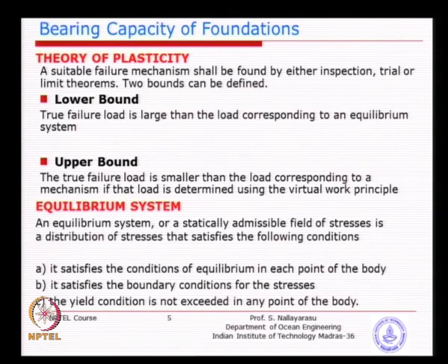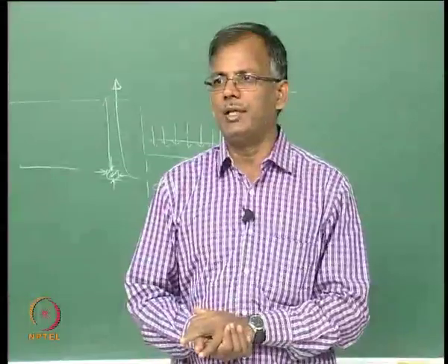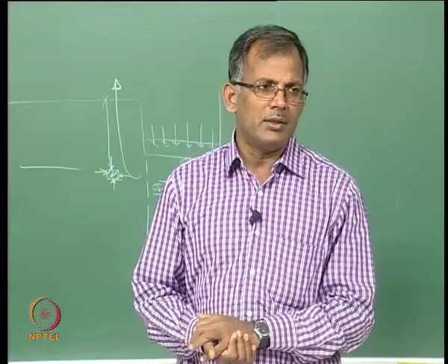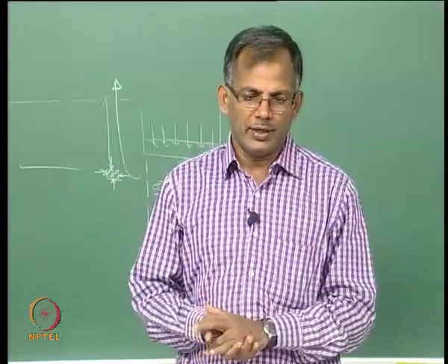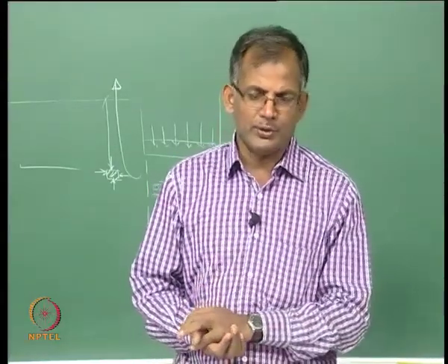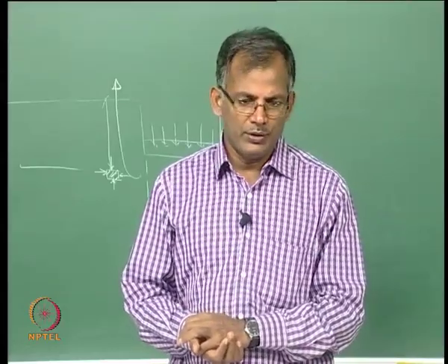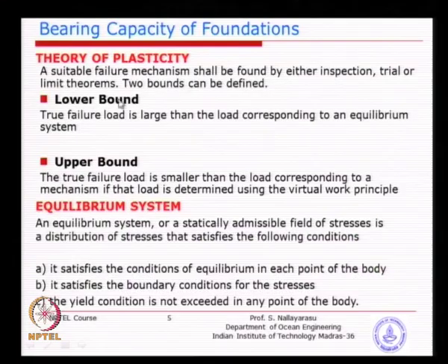For simple types of soil, we will see c equal to 0, that means a pure sandy material, and clay type of soil to understand. But when we go to a comprehensive c-phi soil, the derivation may become a little bit bigger. We will try to derive, but finally I will give you the equations which could be used. So, the basic idea is, you may have several solutions.